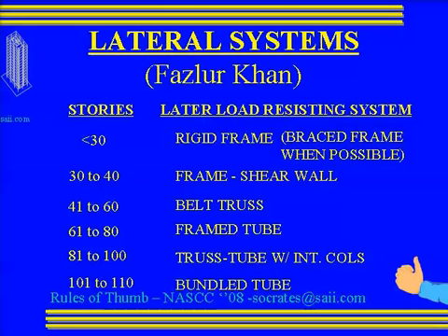This is a direct extract from the late Fazlur Khan, who, of course, you know, if it came from him, it was written 30 years ago, so there are some adjustments to this, but I copied it verbatim to give him credit. He said if it's less than 30 stories, you can usually use rigid frames. Nowadays, actually a braced frame or a combination of the two is used quite a bit. 30 to 40, you definitely need some sort of interaction with shear elements. He's calling it frame shear wall, but the shear wall or a braced frame, I give you the same thing.